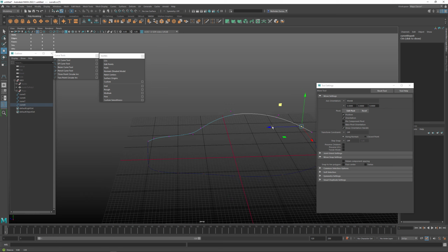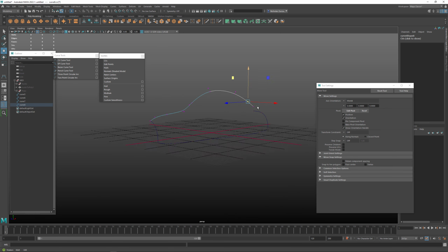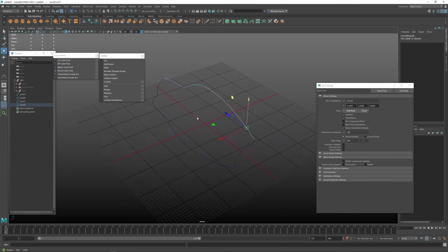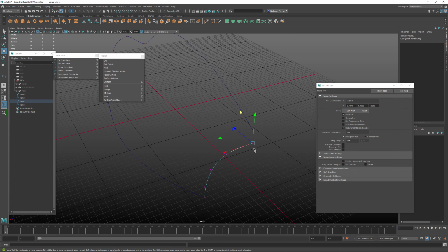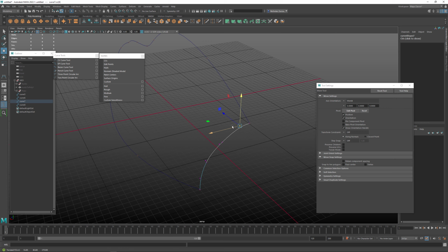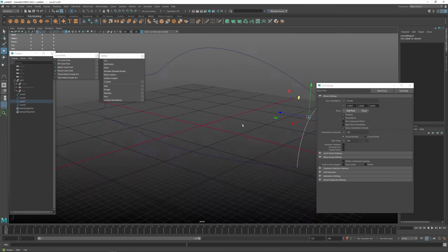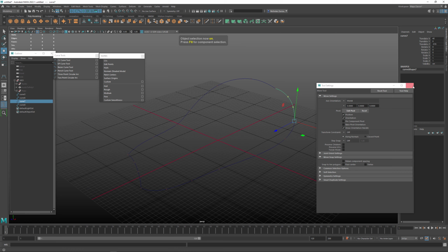So I'm going to do this here like that. And then because I like this as the sweep of the center of whatever this body is going to be, what I'm going to do is take this curve that we have here and snap it to this here. So I'm going to hold down V and then snap up here, and then this will become the beginning of that surface on the back here like this. Okay. So I should have everything I need to create our surface.